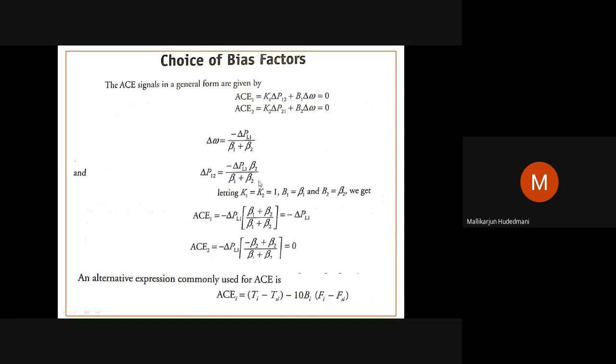I have shown only one part, where there is a change in load in area 1. As ACE of that area is non-zero, it turns out as the shift in load only. ACE2 naturally turns 0 because it should not respond for that. When I have a load change in area 2, I should experience non-zero ACE2 and 0 in area 1.